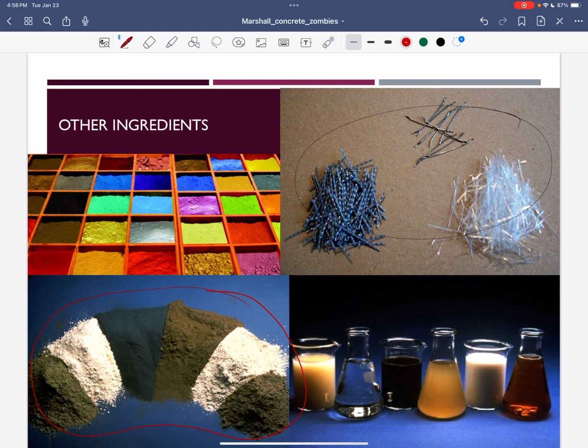That volcanic ash also has some of those chemical properties of cement. And so we may have different replacements or additions that we use for different properties. And then we have certain chemicals that we use for certain properties as well, maybe to make it flow better or to get that air distribution in there, or for it to set faster so that I can drive on it faster. All kinds of different chemical admixtures can be used.